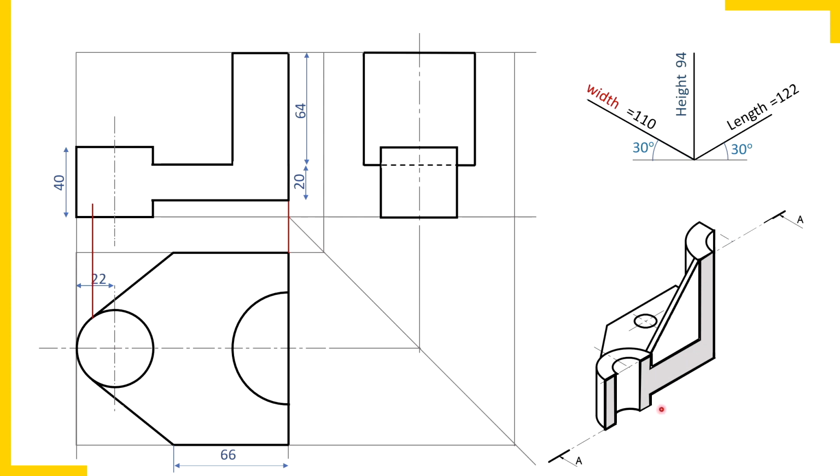Check here, I've cut the object. Can you see this surface? This surface is in one plane. The corner here on the back side, a similar corner was there on the front side, which we have removed. That is why corresponding to this corner, the dark edge is removed, and on the back side there is a hidden edge, not to be shown in sectional view. We are drawing an orthographic sectional front view.